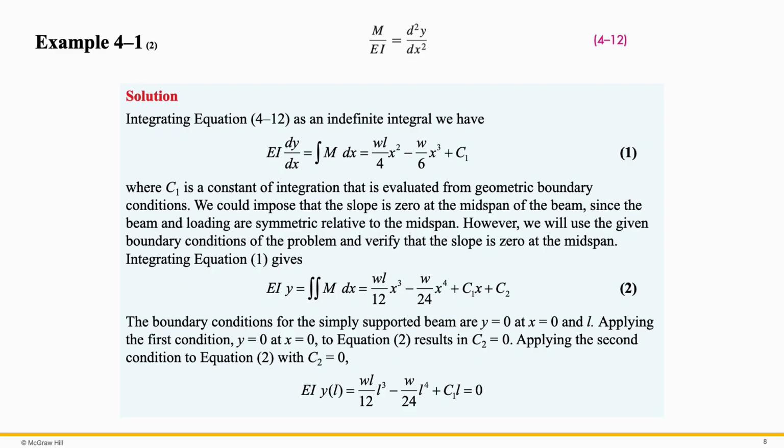And then when we take the integral of the first equation, we obtain the deflection function, which is represented by y, and we obtain the second equation. But naturally, we need to also include the second integration constant C2. C1 and C2 integration constants are obtained by applying the boundary conditions. We know that this beam is simply supported, therefore the end deflections must be equal to 0. When x is equal to 0 and when x is equal to L, the corresponding deflections are equal to 0, and we can determine these C1 and C2 constants.